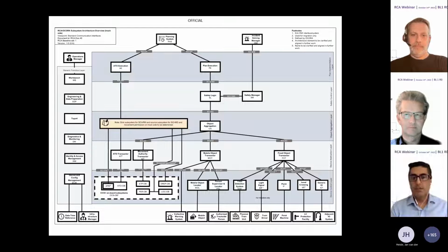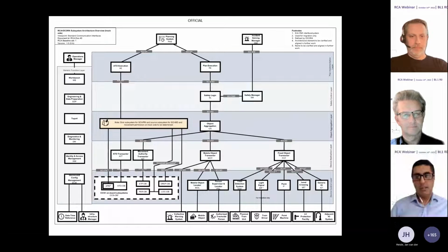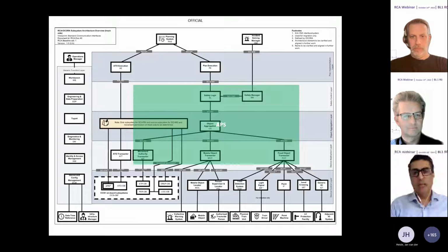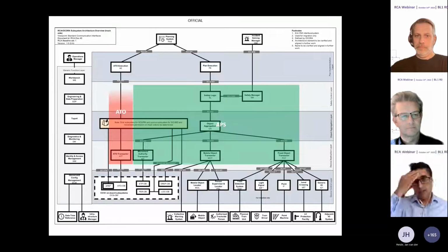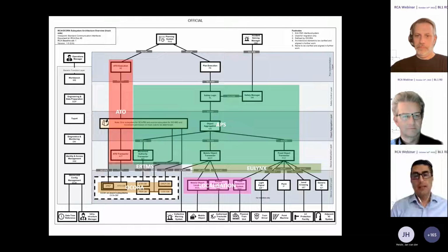And this decision-making process is really important, using this methodology to allow us to take into account and break down into these different subsystems. So these aren't just subsystems that we've dreamt up. This is more a case of taking a methodology and then using that information to meet those needs and defining these subsystems. So importantly, we have something called APS, or Advanced Protection System, and people may know that as the interlocking and RBC in one system, and that's what provides this centralized safety logic, which manages only geometrically defined permissions. And we also have ATO, which has a similar architecture,